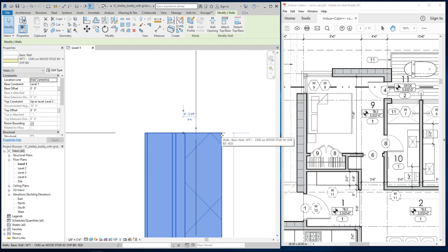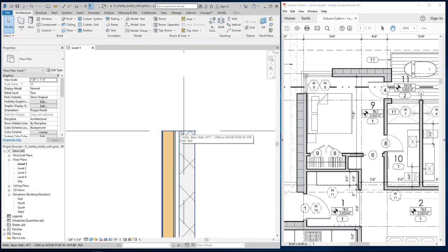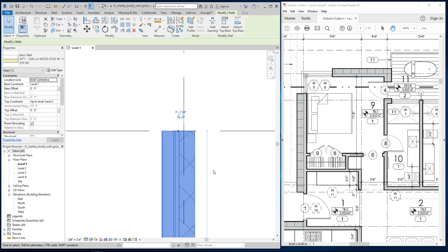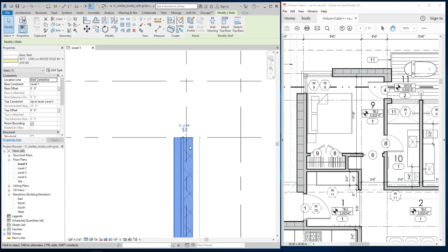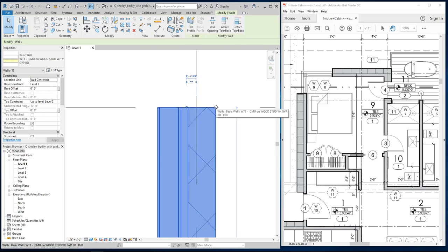Okay, this is actually a really big topic because if you have to change the wall assembly on a project you're working on, and your exterior wall is defined so that maybe your square footage is perfect, right? If you have your location line located at the center and you change all the exterior walls, all of a sudden you have 3 extra inches all the way around the perimeter of the building, right? Let's say if it's gross square footage. So that's not very helpful when you want to maintain a footprint, right? I wanted this wall to be lined up with grid line 3. And with a location line at the center, I just added a bunch of wall on the other side of grid line 3. Let me undo that.